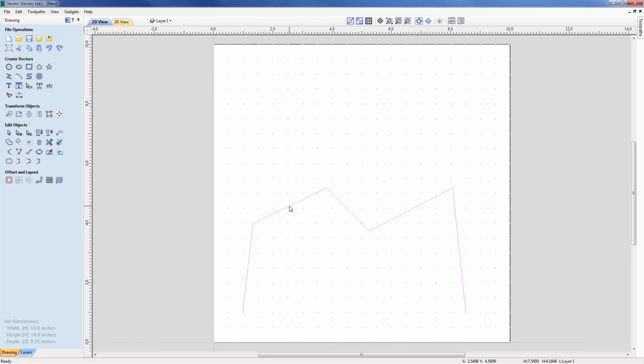Now, of course, I can use the move option on the menu, but what I can do is just click on this now to take it into the transform mode, and then hover my left mouse key over any one of the points, and I can start moving this around. So in this case, I want to take this point, and I know that I may want to move this a distance in Y by 3. So I'm just going along orthogonally in the Y direction.